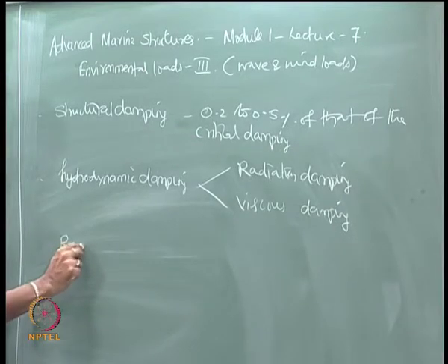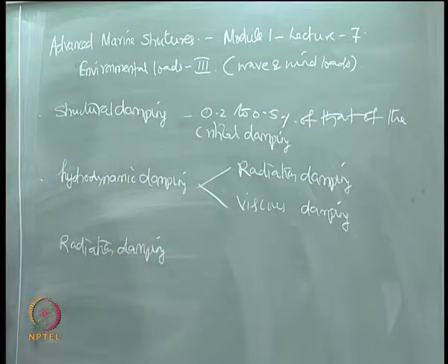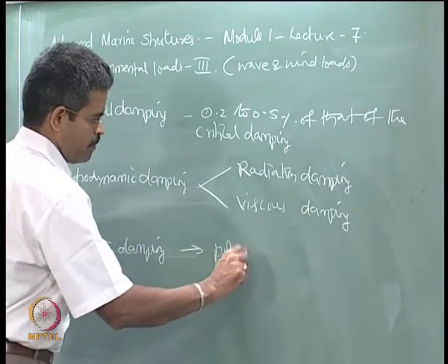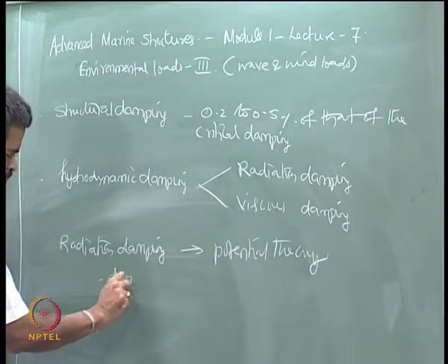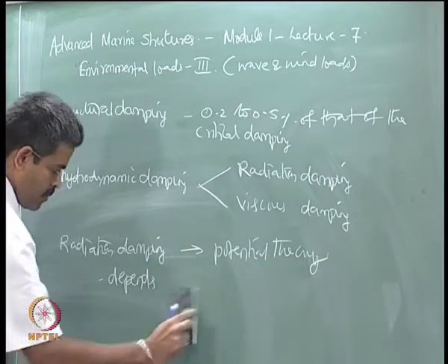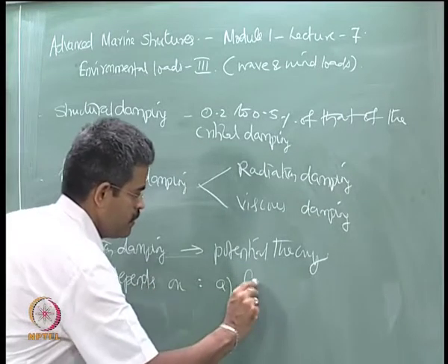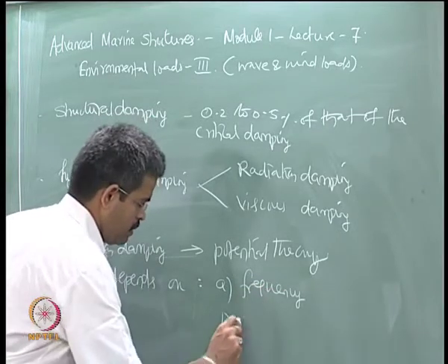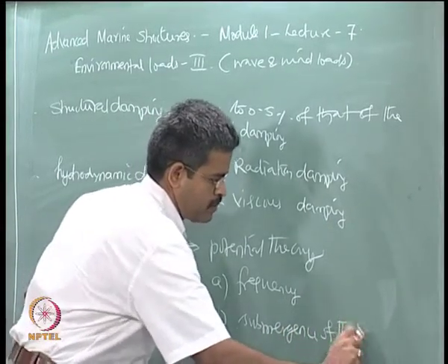The radiation damping is evaluated using the potential theory and it depends on frequency and submergence of the structure.